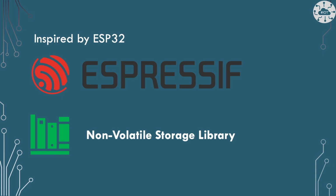To be honest, there's a lot to think about when you're writing to flash, and doing that using these base level SDK APIs all the time is actually a pain. I program on some other platforms as well as the Pico, one of which is the ESP32 and the Espressif platform for that microcontroller. Now that's got a really lovely library called Non Volatile Storage, which actually handles all of this stuff of writing to flash for you and makes life a lot easier.